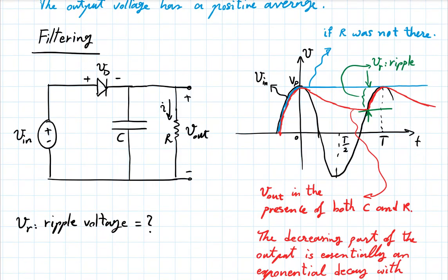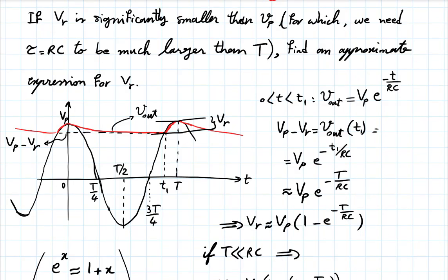At the point just before this peak, the capacitor current becomes 0, right? Because the dV by dt becomes 0. After that peak, the capacitor starts to discharge, of course, but all of that discharge current is going through the resistor, actually, right? Not through the diode. So during all this time, the diode is reverse biased. There is no current up until this point when the diode turns on again.